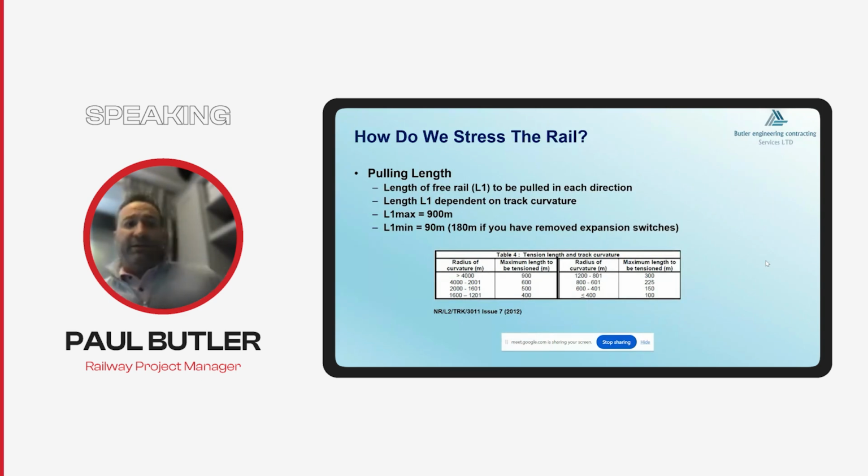So your pulling length is classed as the length of free rail to be pulled in each direction. As I said, the length of L1 depends on track curvature. It's generally got a maximum of 900 meters, but it also has a minimum of 90 meters, although this can be 180 if you've removed expansion switches.